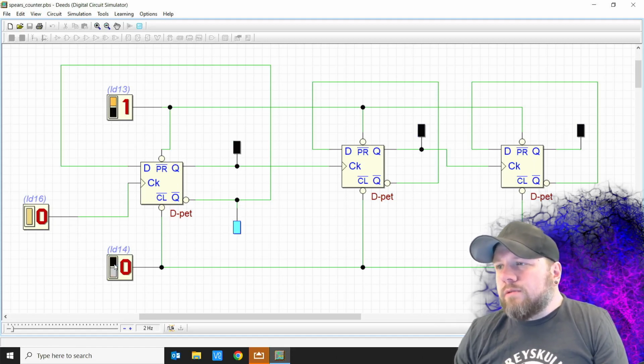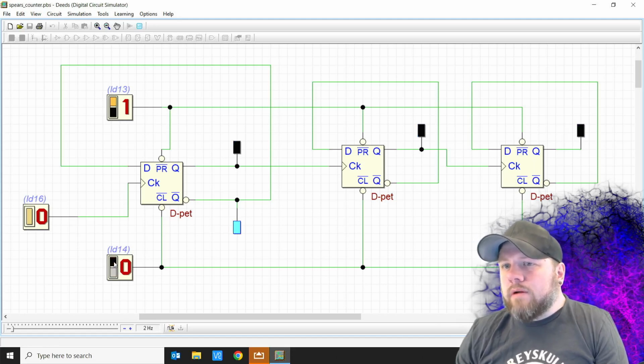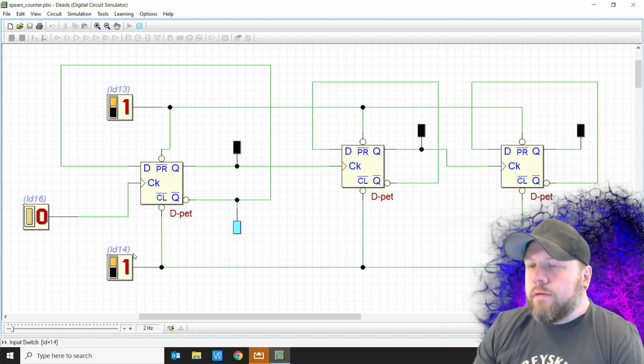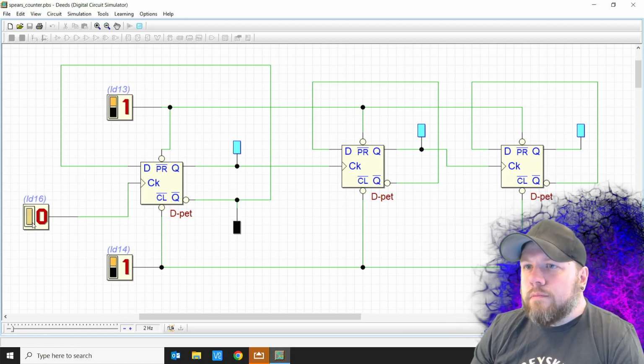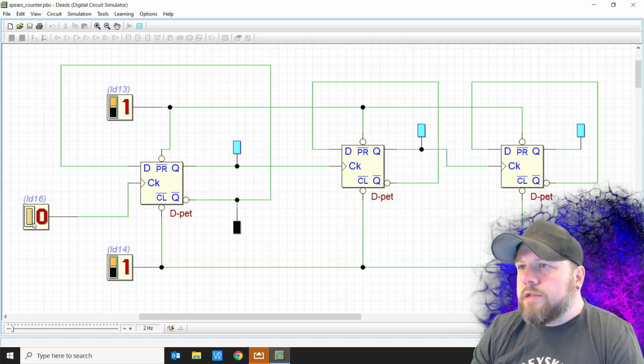All right. So this is what's called asynchronous. Like this will happen regardless of what the clock's doing. All right. So synchronous is we're having to deal with that clock. We can drive everything asynchronously down to 0. So we got 0, 1, 0, 1, 0, 1, 0, 1. Notice that every other time the thing before it changes, the thing after it changes.